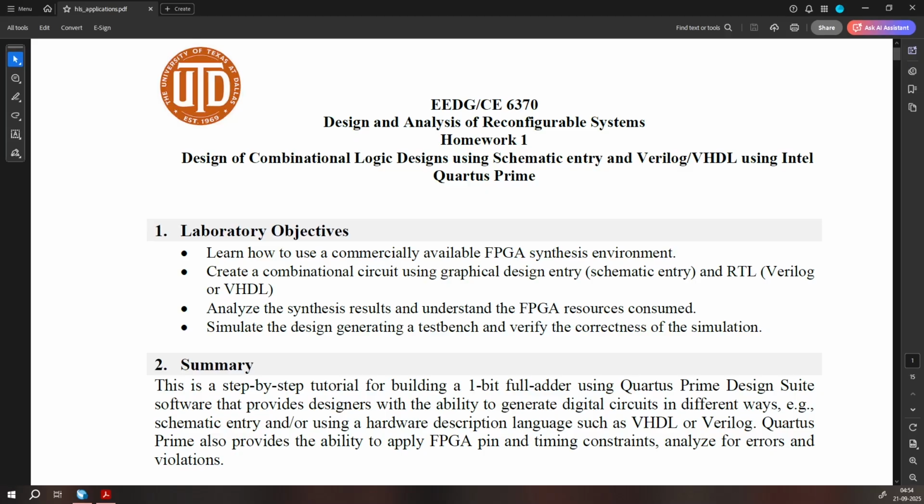After doing all this, we are also going to be implementing an n-bit full adder for 4, 8, and 16 bits to see how many resources are being consumed in two different styles of designing: one is behavioral and the other is structural. So our primary hypothesis is that behavioral design is going to consume fewer resources and have better performance compared to structural. But we'll have to verify this quantitatively by designing and synthesizing for the board constraints.